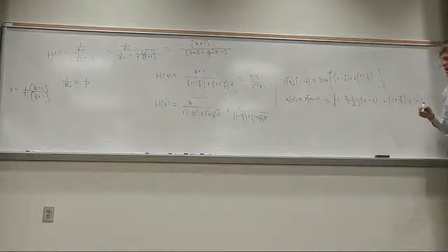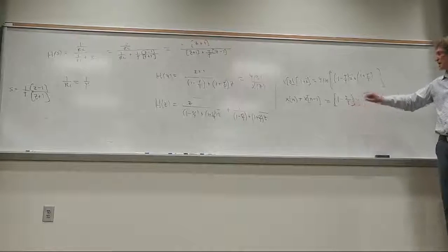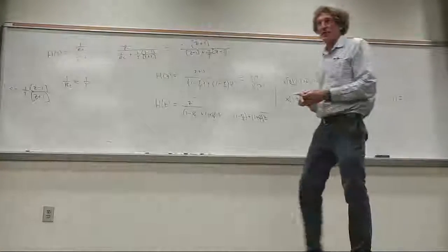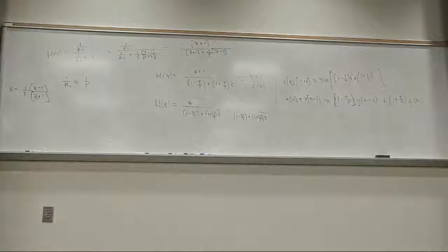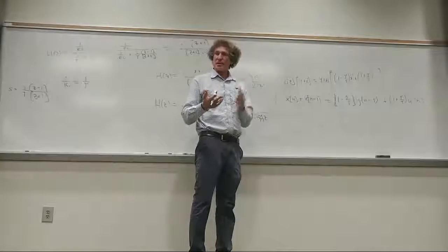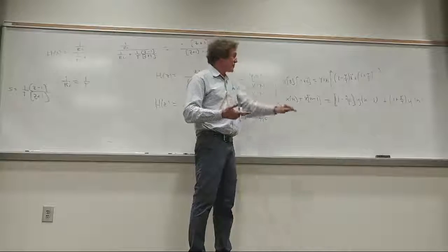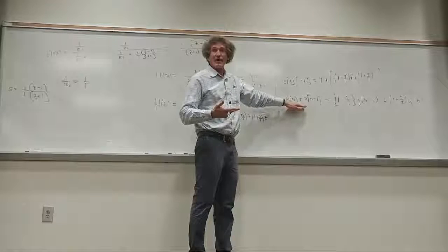And now you have a filter. Listen to me. If the sampling frequency on this is T of s, and tau is RC, pardon me, not 1 over RC. Tau is RC. Then if you take a digital signal and sample it at that rate, and you apply this difference operator, by the way, this is done in the discrete time domain.